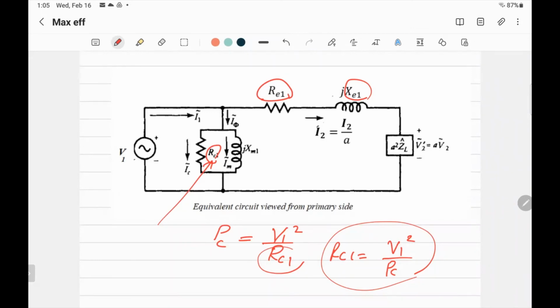It's equal to the rated value in this case. But as I told you, the transformer was 2400/240, and we used the rated value. What about if they told you you are using 200 volts? You have to be aware of that. If you have 200 on the secondary side, use the turns ratio, and you will have the corresponding value here.